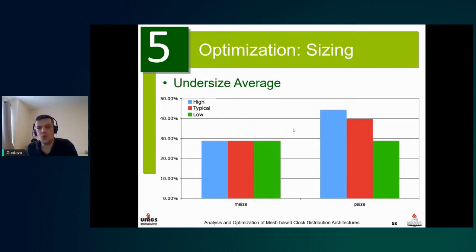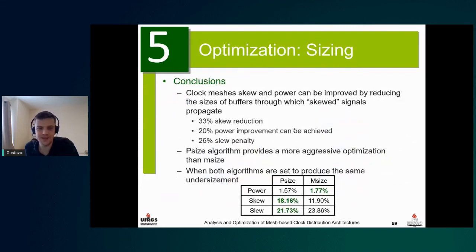So basically, instead of adding dummy capacitance to avoid impacting the delays of the clock tree that is driving the clock mesh, we could try to take advantage of that by using it to reduce the delay of slow paths in the clock tree. And therefore, besides reducing the input skew applied to the clock mesh, we would be reducing the power consumption also, because we would pad it with smaller dummy capacitance. But this was not explored there.